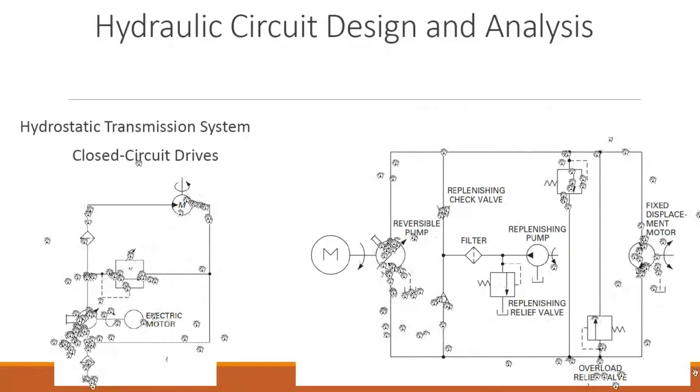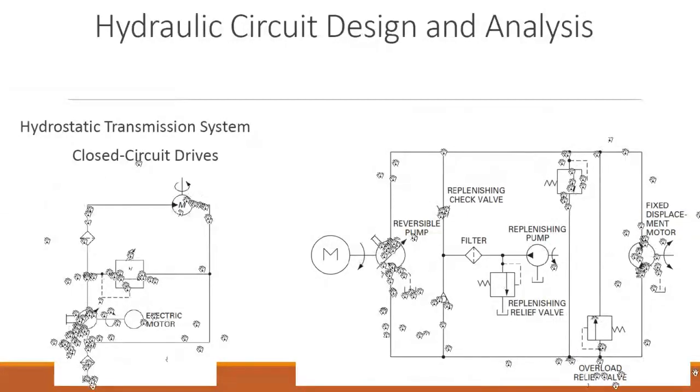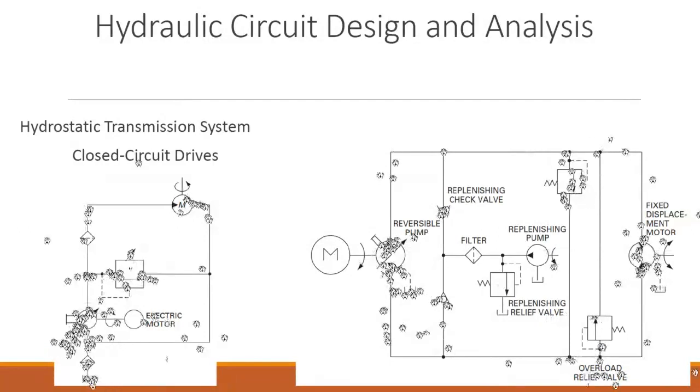If by any means the motor is stuck, or the load is more than the capacity of this motor, it means the motor will not run and the pressure would keep on developing because the pump is continuously pushing the oil into the circuit. So in that case, this will open, and instead of going to the motor and damaging it, it will just continue going like this, or in the opposite direction it will go like this.